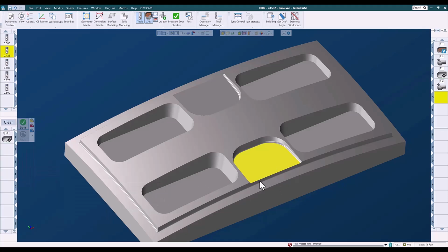So on this side, at 0 degrees, the raster lace cut is going to start on the front and work its way to the back. So I'm going to do these separately because I want both of them to work from the outside in. If I did both of these at once, this one would work from the outside in, this one would work from the inside out, because the direction of offset is going to be toward the rear. So let's go ahead and do that one.